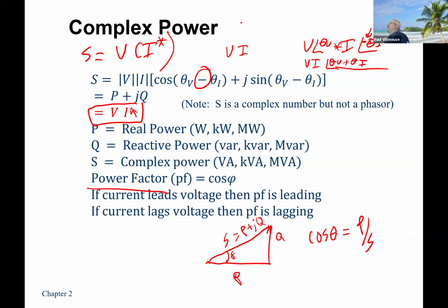That's just what it is. That's the industry term. So if you want to work in renewables and you want to connect to the grid, which almost all renewables should be able to, that's what the inverters are rated for. They'll tell you a power factor and they'll tell you if it's leading or lagging. So there's a lot of electrical specifications on an inverter, right? And these are pretty darn important. So understanding who or whom is leading or lagging is the biggest thing. So it's always current. What is current doing? Is current leading or lagging?